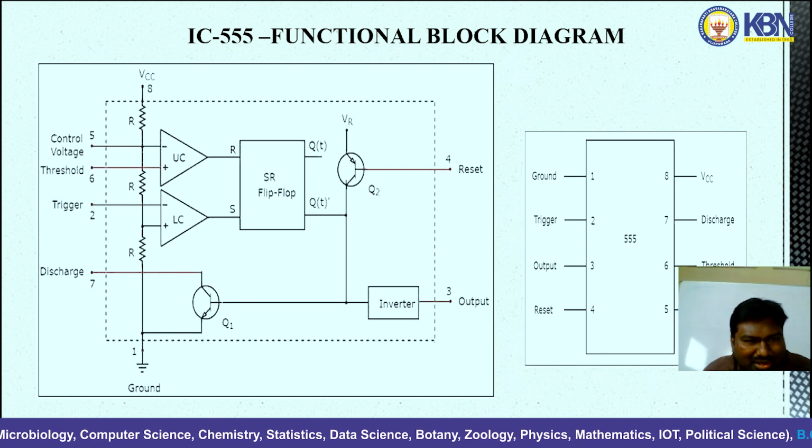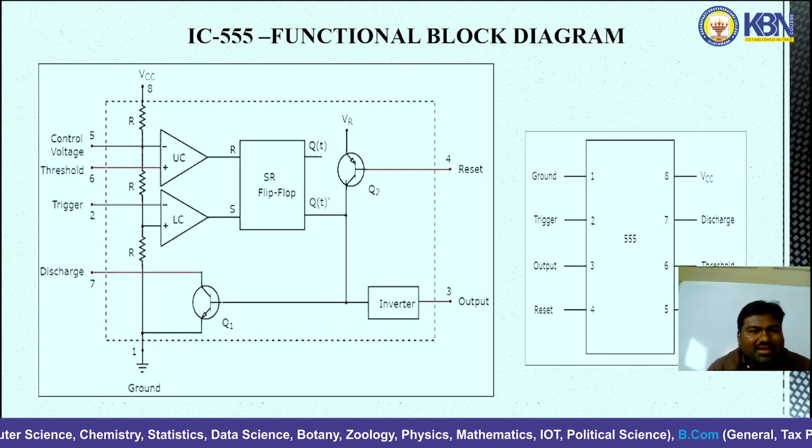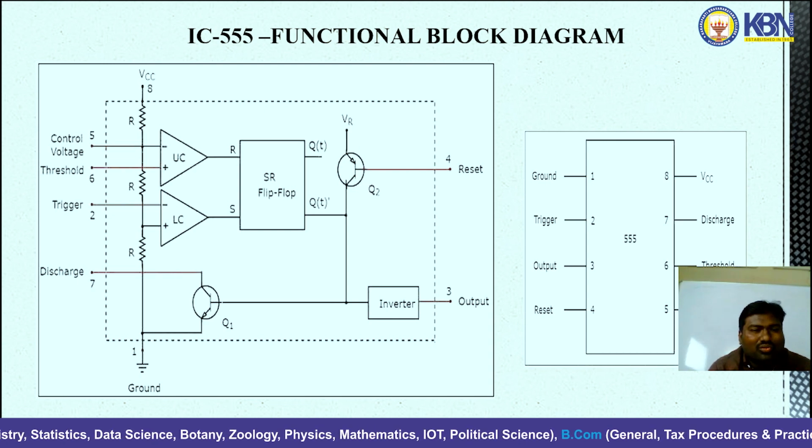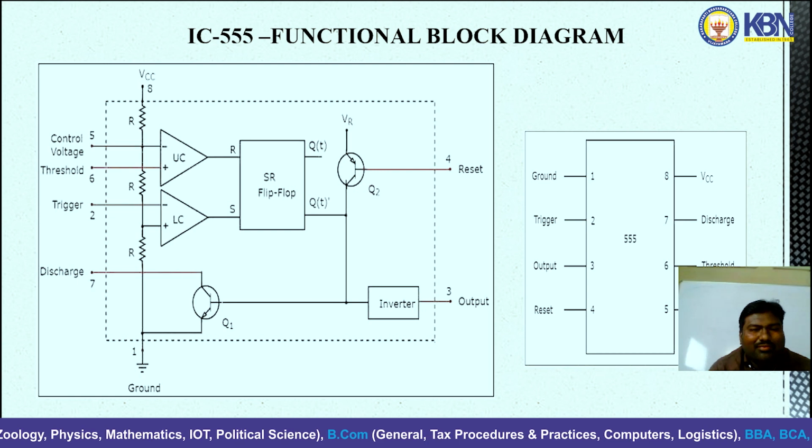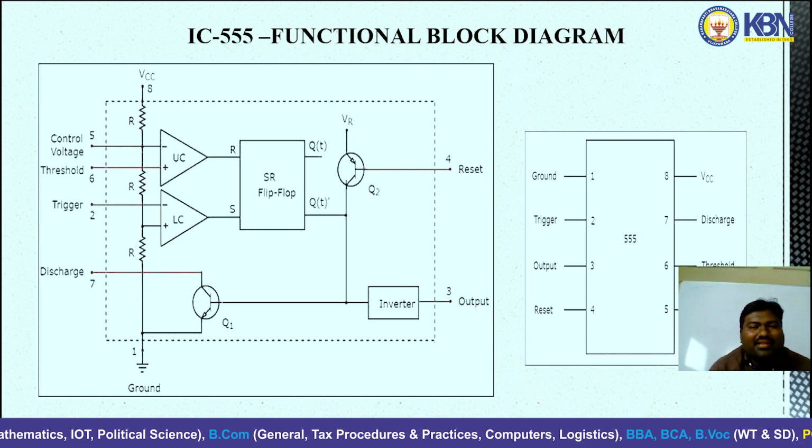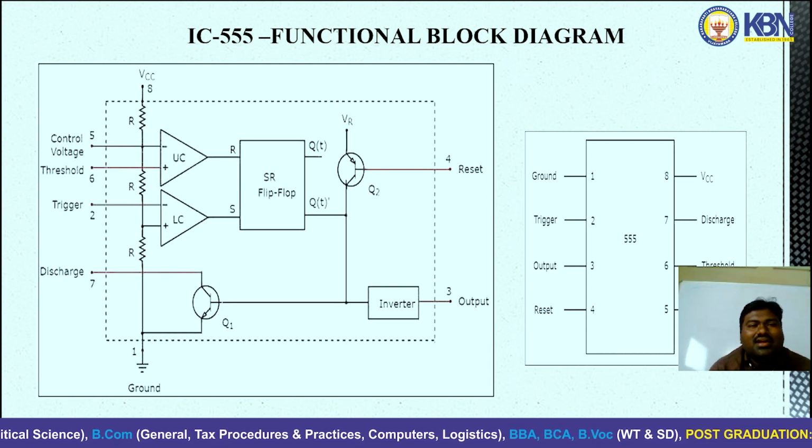In the block diagram there is an upper comparator and a lower comparator, both connected to an RS flip-flop, which is then connected to an inverter and a transistor.